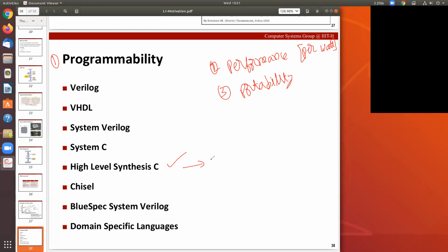And in this course, we use what is called an OpenCL framework for hardware specification. And under the hood, OpenCL uses HLS. So it is like this: you have HLS, and the specification that you make in HLS gets mapped to Verilog or VHDL by the compiler. This is HLS, this is C++. And then OpenCL is one level above.